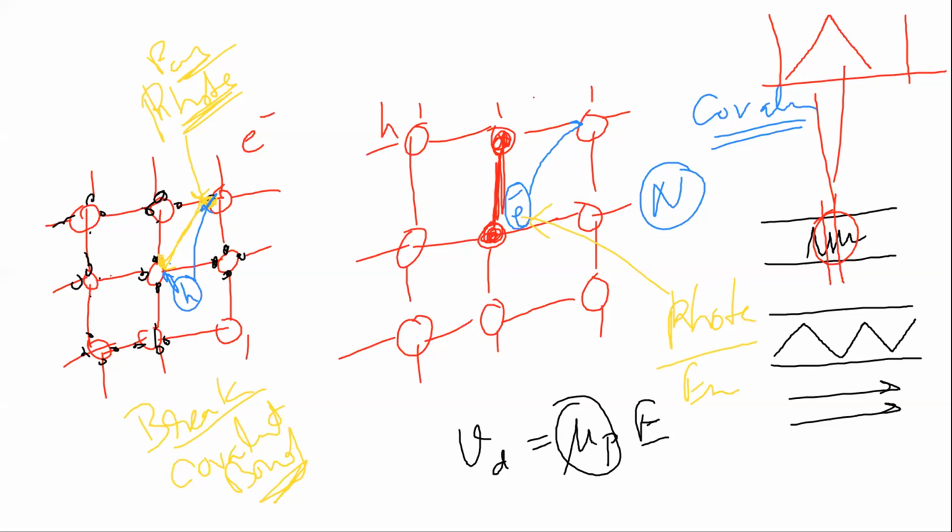So, first of all, I didn't get the second part of the question. Oh, what he's saying is that the N-type conducts really well, so he's saying low energy. Basically what it means is, given voltage, you get higher current, right? For a given area, W over L, you get lower resistance. Why use P-type at all? We always want higher efficiency. Why use a P-type at all?